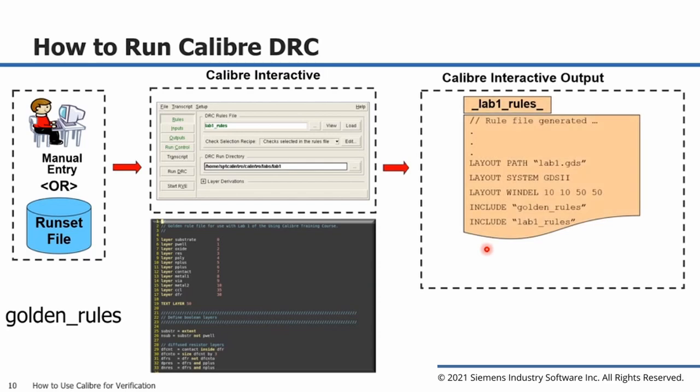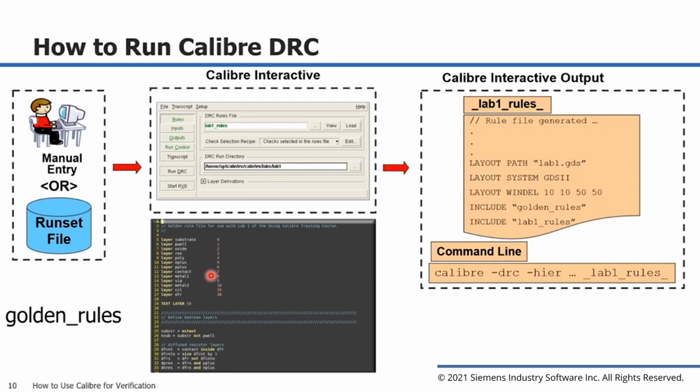And when you execute, it's the same as though you use the command line to execute. For this particular instance, if you click on run DRC here, it will actually go through this command, these golden rules, and check it, inserting all the necessary information which you entered in your GUI in a text field, and it will run exactly as if you are using the command line.